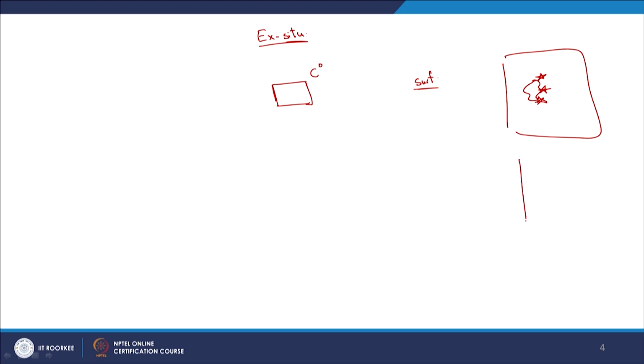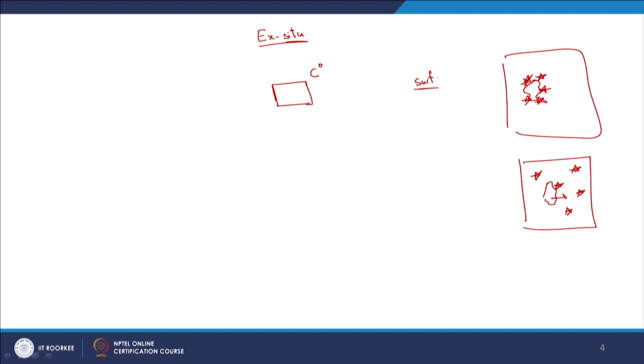So, after equilibrium is reached, what will happen? This is the initial case, when most of it was adsorbed on soil, and after equilibrium has been reached, I will have most of it in the surfactant now, right. But what does it depend upon? There is going to be an equilibrium between the contaminant adsorbed on soil and the contaminant concentration in the micelle, or in the surfactant, pardon me. So, when will you maximize your efficiency? When the concentration difference between the surfactant and your soil is greater, right.